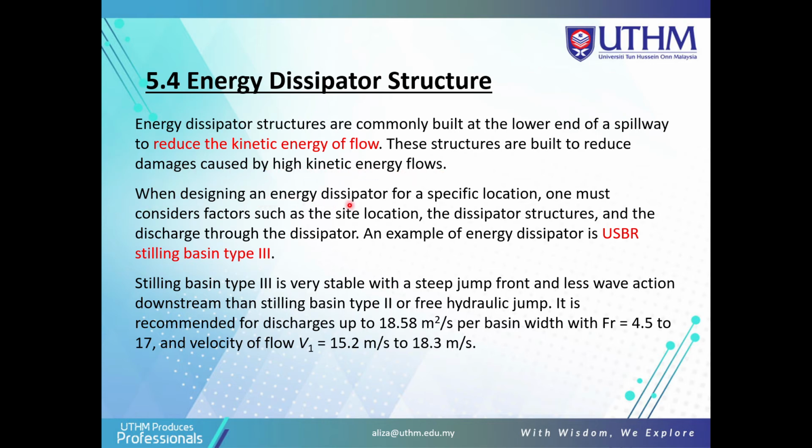When designing an energy dissipator for a specific location, one must consider factors such as the site location, the dissipator structures, and the discharge through the dissipator. An example of an energy dissipator is the USBR Stilling Basin Type 3. Stilling Basin Type 3 is very stable with a steep jump front and less wave action downstream.